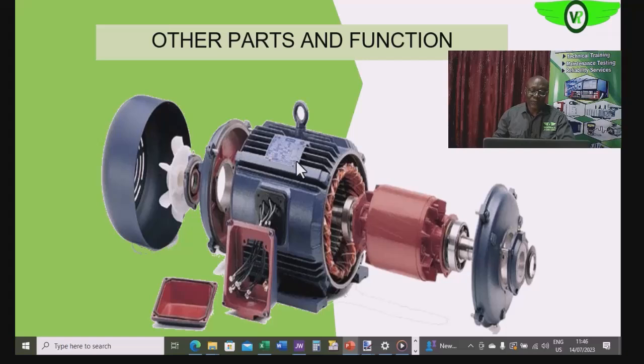The function of this fin-like structure is to retain the air on the frame as much as possible, so as to enable effective conduction of heat that will be carried from the winding during operation to the frame of the electric motor, away from the electric motor. All of this helps to effectively cool the electric motor.